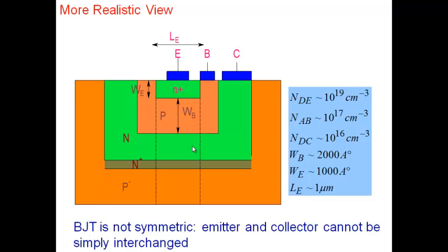And you know the concept of integrated circuit. Integrated circuit means I have to make both the transistors, the resistors, the interconnect, everything on the silicon substrate itself. That's the concept of integrated circuit, that we make the entire circuit on the silicon substrate itself. So if I have 2 transistors, I want those 2 transistors to be isolated from each other. So just imagine in your mind that I have one transistor here and another transistor fabricated side by side. One more transistor, exactly the same thing. The other transistor also has N plus, N, P, and N plus, and is fabricated by the side of this particular one.